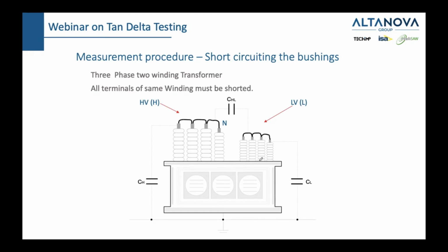So you have some indication of what needs to be fixed. When you do some other DC test, you just get one number, and that one number cannot tell you where the problem lies. Here you get a minimum of 3 numbers, and effectively you will get 9 numbers, or even maybe 11, because you will also be testing each bushing by itself.